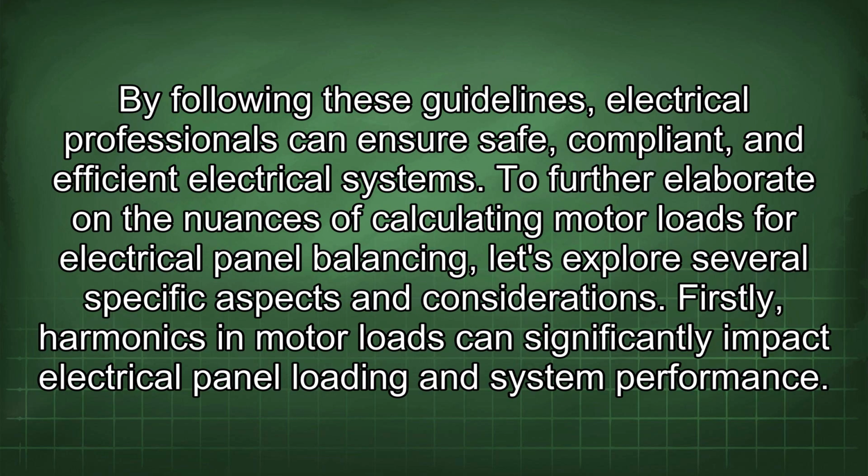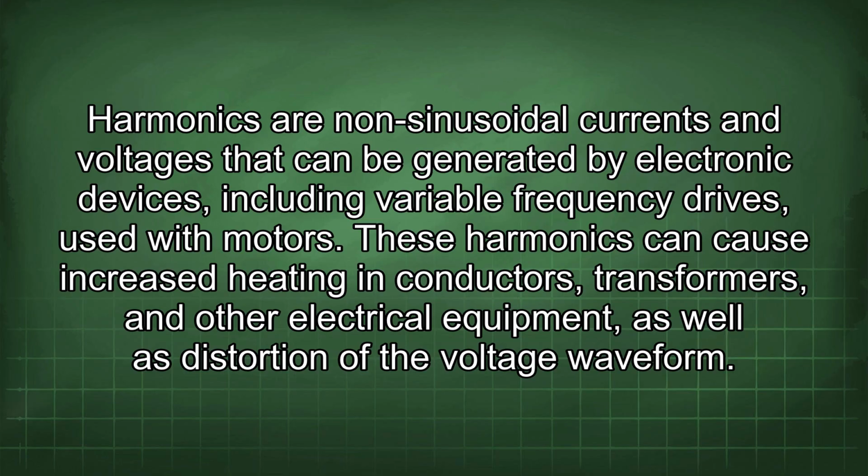To further elaborate on the nuances of calculating motor loads for electrical panel balancing, let's explore several specific aspects and considerations. Firstly, harmonics in motor loads can significantly impact electrical panel loading and system performance. Harmonics are non-sinusoidal currents and voltages that can be generated by electronic devices, including variable frequency drives, used with motors.